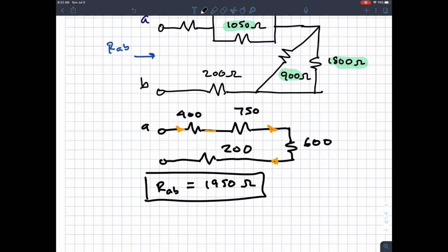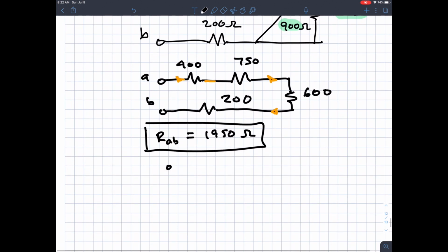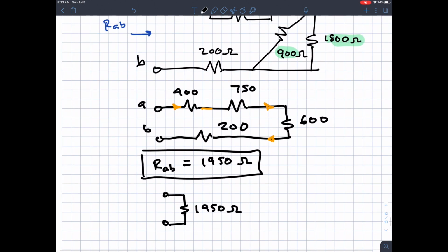So I can replace this complicated circuit with an easier circuit, and those would serve equivalent purposes as seen by the battery that was trying to drive that load. It would take the same amount of current to drive that load with a given battery. So those are a couple of examples. You need to practice those. Again, my experience is that it takes a while for some people to see it, especially the parallel combinations. But once it clicks, it becomes fairly obvious how to do equivalent resistance.